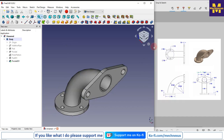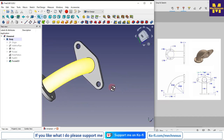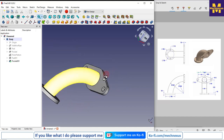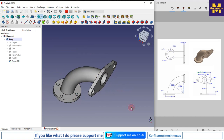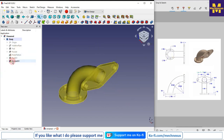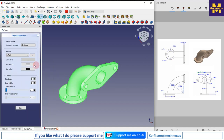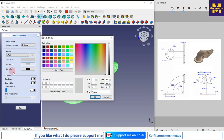Now I will switch to the isometric. So this is how we have completed our model, pipe with flange. Now I will give the approximate color as per our isometric. So I will go to the appearances and I will click here on the shape colors and I will give a very close color to our model.